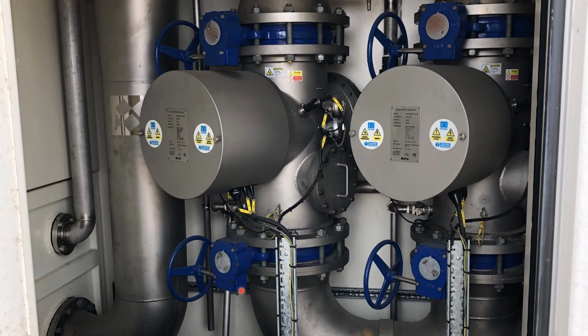I turned the reactor on for 180 seconds. The UV exposure time was short as the water in the reactor immediately began to heat up due to the no flow condition, or static condition, and I didn't want the reactor to overheat and trip the high temperature shutdown limit. I then shut the reactor off and collected samples of the water that had been UV irradiated. I analyzed for ammonia content, peroxide content, and cyanide content before and after UV exposure.